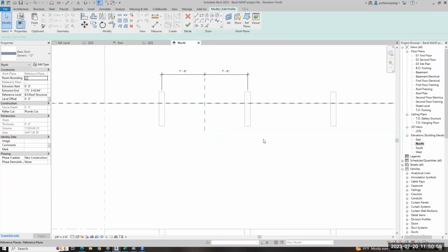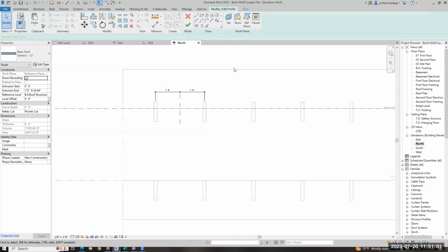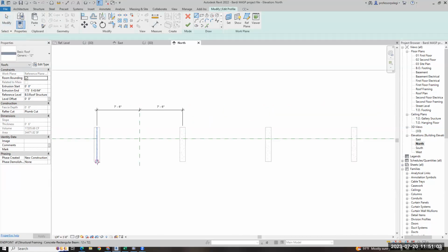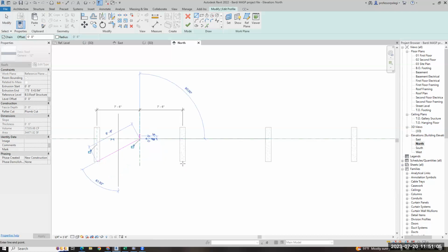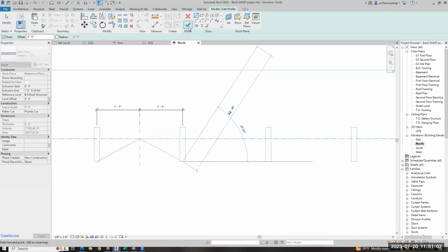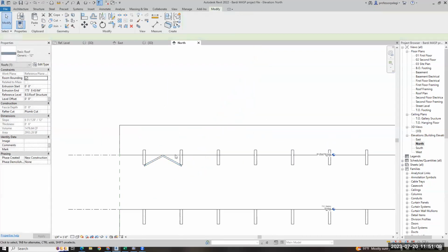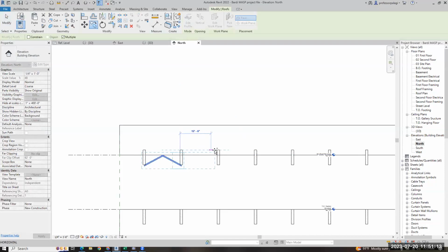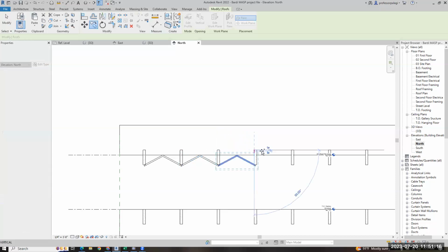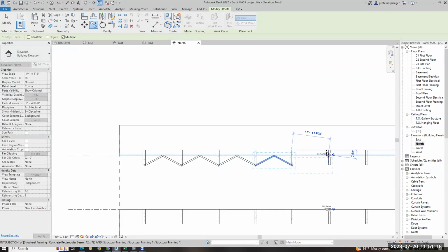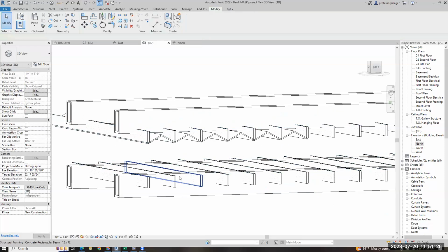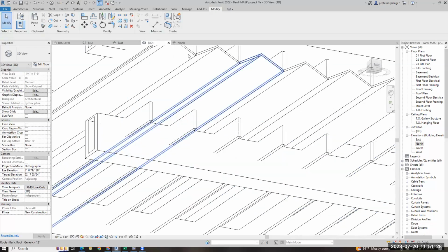So now what I'm gonna do is I'm drawing a profile that goes from there to there. So even if I just do this and go boom, boom. Okay, I can actually take that, copy, and for some reason it doesn't like array. I found that when you array a profile like this, it arrays one over and then all the rest sit on the beginning. So we could look at that and say, okay, well, I'm getting what I want underneath.